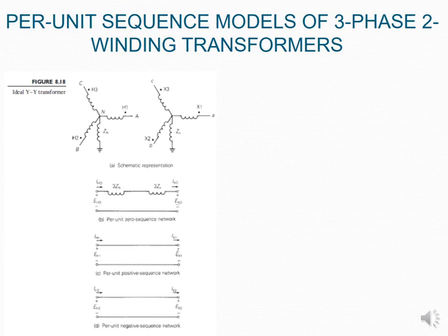Then we look at what we call our three-phase two-winding transformers, and this is what they would give you when you move them into a sequence type of network. You can see that you've got your three phases A, B, and C, and then you've got the Zn going through to your ground.